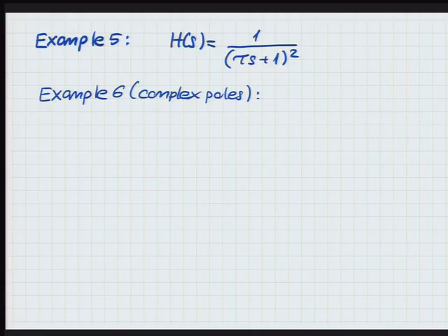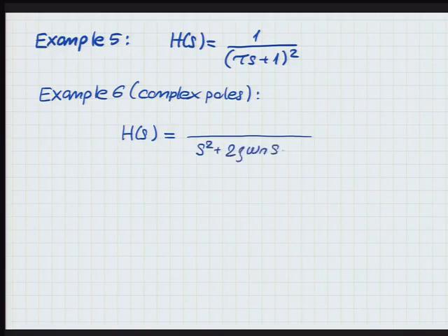What is our famous transfer function for a second order transfer function when the poles are complex? Remember that funny parameterization? Looks funny, but it's actually useful. Omega n squared over s squared plus 2 times zeta times omega n s plus omega n squared, and we put an omega n squared here as well, the purpose of which is to make sure that H0 is 1, right?